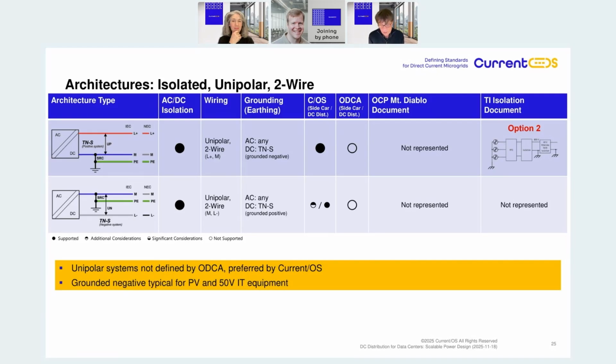And what is also important to understand is that these architectures have a positive effect when you have to deal with stray currents. To give an example, in the picture below you see a negative system. In telecom, it was quite common to use minus 48 volt to connect to equipment.